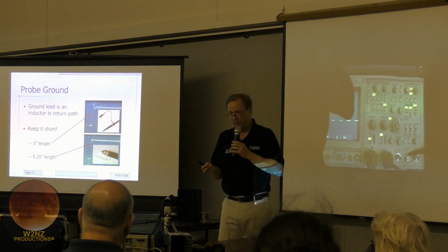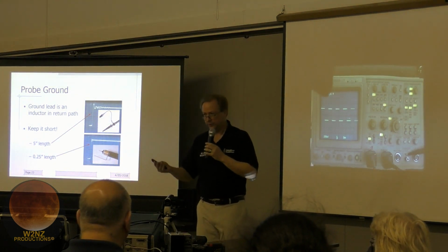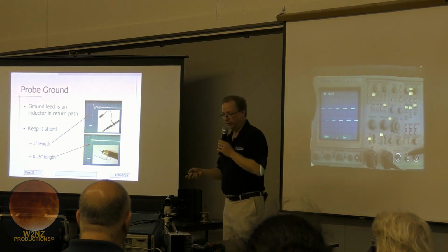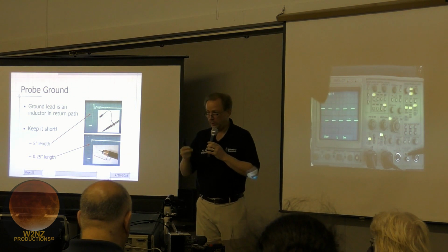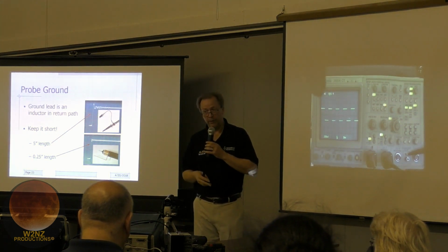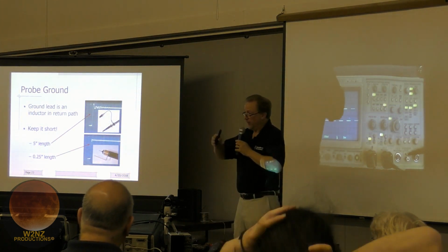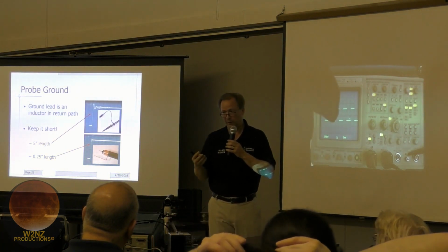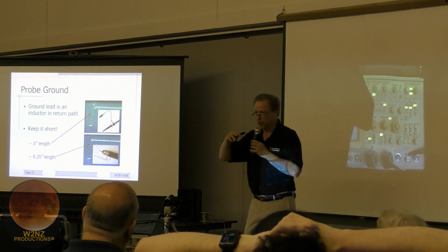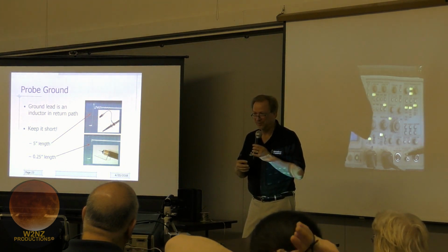If you don't connect the grounds and you're probing an audio signal, who cares? Right, who cares if you have a couple of nanohenries of inductance? If you're probing a logic signal with some fast edges, or you're probing an RF signal, then it can matter a lot. What's odd is if you go really high in frequency, then the capacitive coupling through ground will oftentimes be enough to kind of get away with it. But I just wouldn't believe the amplitude of the results, okay?